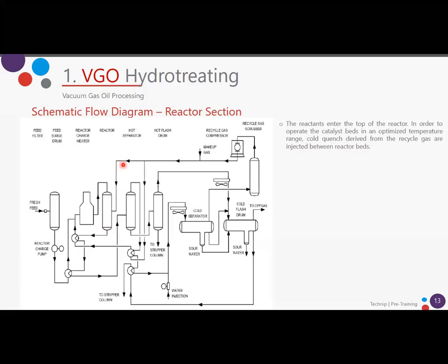That is the same recycle, but without this preheating of the recycle. So some of this recycle goes here and is injected in the reactor as quench. Remember the importance of this quench we saw in the safety moment. We have to avoid any temperature runaway in the reactor.